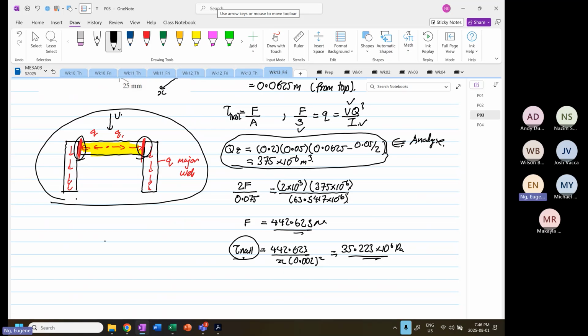Now, for the shear stress of the nail, why can we just divide by area? We are calculating this stress over here. If I pick an element, if I were to draw an element down here, the shear stress is in this direction, and the shear stress acts in the other direction. These two shear stress magnitudes are the same. So this is the cross-sectional area, and that's why we take this cross-sectional area and just do force divided by area. Okay, that's straightforward. Are we clear?